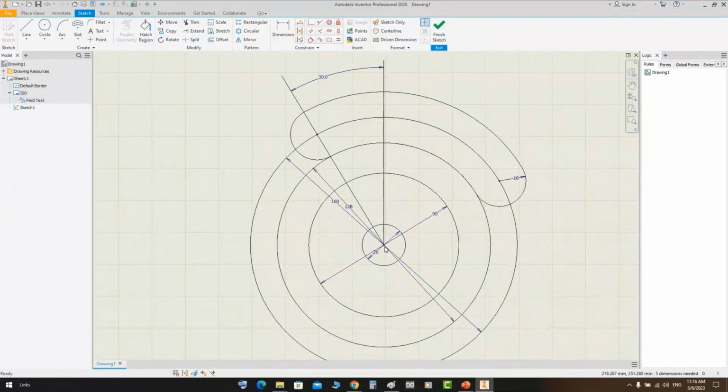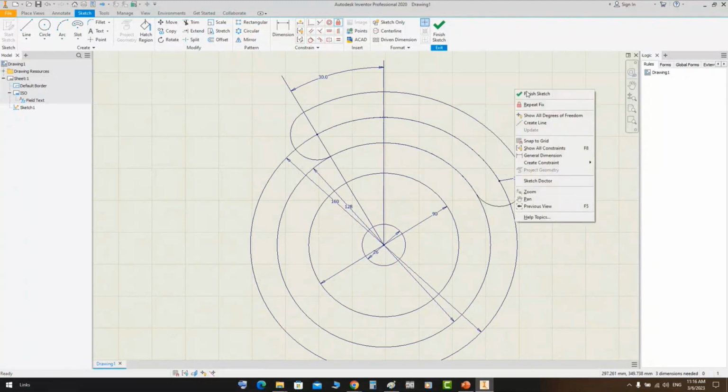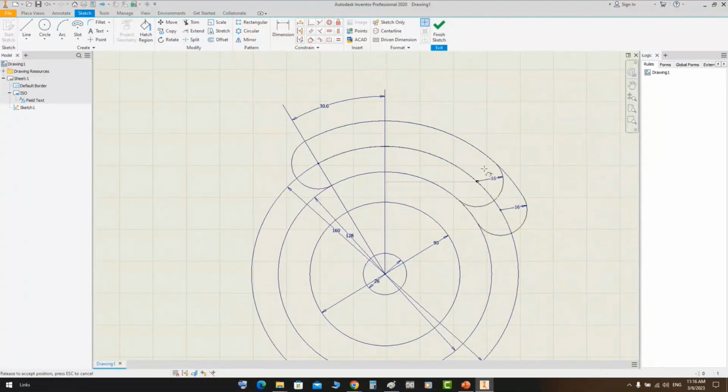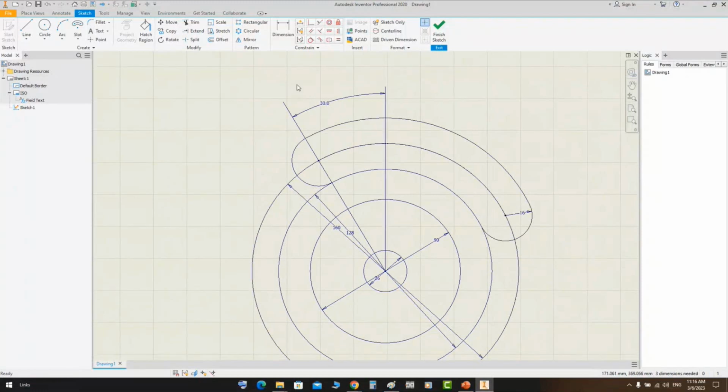Now you can figure that the second end will be moved. Let's fix this point at the middle. We need to fix this point to avoid moving on the drawing area. So let's fix that. Now you can figure that if you try to move, the end of a slot will be moved. You can make the same feature by drawing another line with 30 degrees and coincident to this point to this line, but we will make it by using another feature, which is